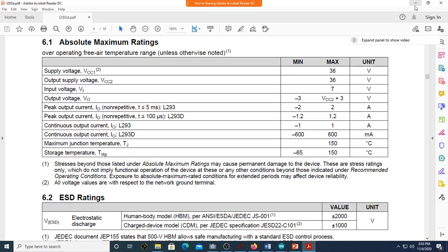Sir, here they have mentioned input voltage VI, right, sir? Where? Okay, here, the third one. The input voltage range was 0 to 5 volt that you are applying to that buffer input. That's what we said, 5 volt, right? 5 volt is the typical voltage. These are all maximum ratings. Max. Okay, sir. This is maximum 7.